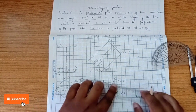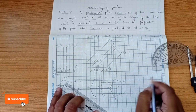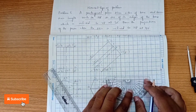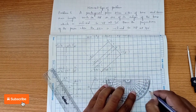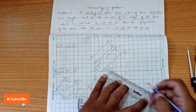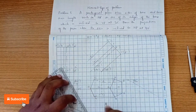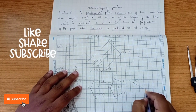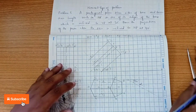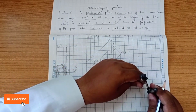Now we have to draw an angle line for the base edge inclination. So for base edge inclination we will draw an angle line like this. Inclination to HP 30 degree. So we have to make sure our third position diagram should not merge with the XY line. Okay, so when we construct, from D1 to C1 we can cut the arc. We have to place the resting edge on that angle line.